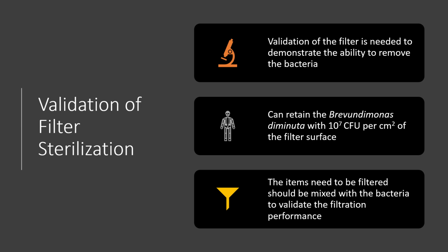Furthermore, validation of filter sterilization requires real-world testing. The items that need to be filtered are mixed with the test bacteria to simulate actual filtration conditions. This ensures that the filtration process performs as expected under practical circumstances, validating its effectiveness in removing bacteria and maintaining sterility. So, validating filter sterilization is essential for ensuring the safety and efficacy of filtration processes in pharmaceutical and biotechnology applications. By validating the filter's ability to remove bacteria, retaining Brevundimonas diminuta under high bacterial loads, and conducting real-world testing with test bacteria, manufacturers can ensure that their filtration processes meet the highest standards of sterility assurance and regulatory compliance.